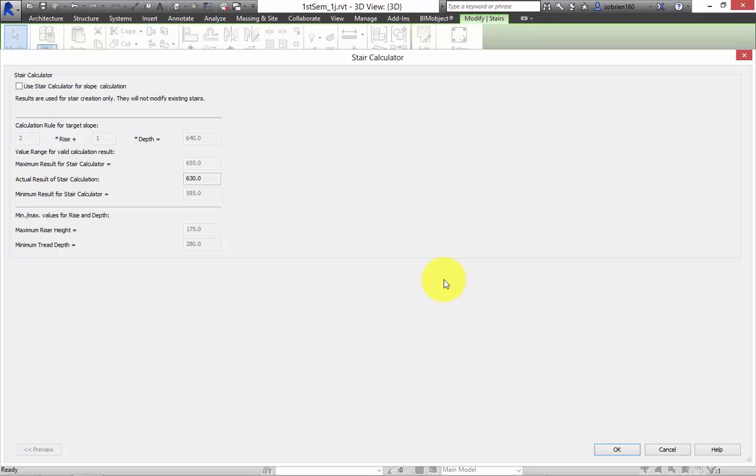So we can be confident that any stairs that we draw in Revit is drawn according to the building regulations, and that's important because if you're making a stairs, and let's say you're making a stairs in a shopping centre, and you design it so that the steps are a little bit too high according to the Danish regulations. If somebody falls down those stairs, then it's your company that gets the medical bills. So it's quite important to get those dimensions correct, because if you make a design mistake like that, first of all, your insurance is going to shoot up, but also you might have injured somebody because they're not used to dealing with that type of stairs.